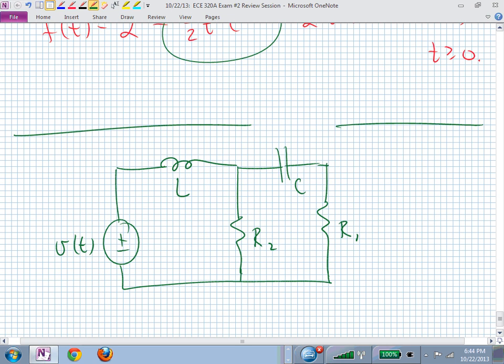This voltage is now R1 I sub C, and I sub C is C dV sub C dt. You now know this voltage from here to there. So here's your reference node, the bottom line, because you know this voltage is just V sub C, and you just calculated this voltage drop across R1, and you can start working your way back.